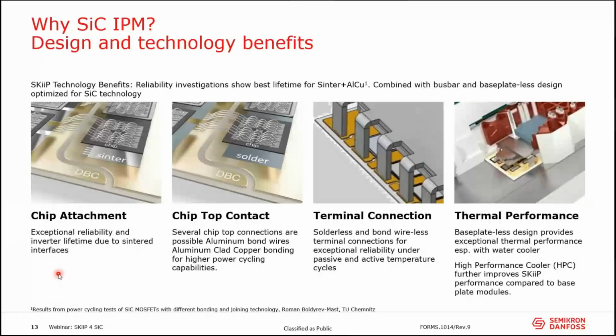For the chip top contact, we still use bond wires, but not standard aluminum bond wires: aluminum-clad copper bond wires, which improve the lifetime of the modules.